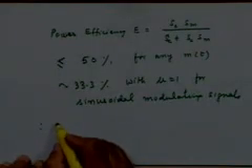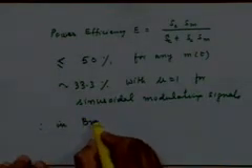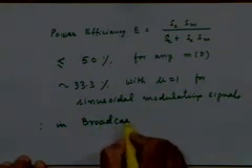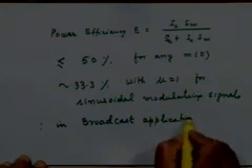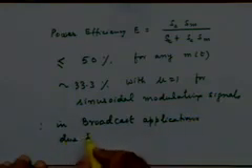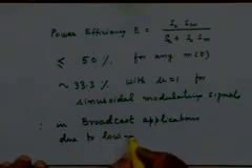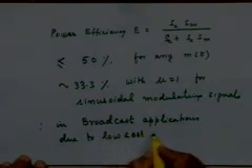So the real application of this kind of thing would be where? In broadcast applications, right? When you're transmitting at one transmitting station and a large number of people are tuning into their receivers and trying to recover the demodulated signal, right? So therefore, the power inefficiency can be tolerated in broadcast applications due to the low cost of the resulting receiver.